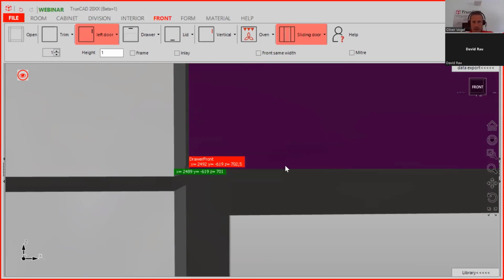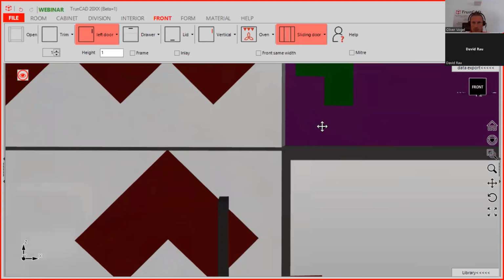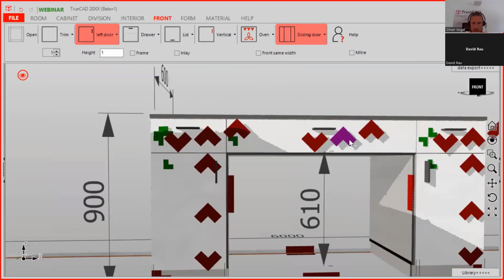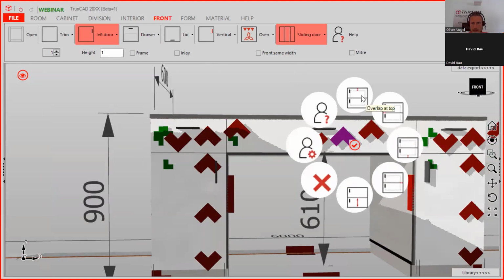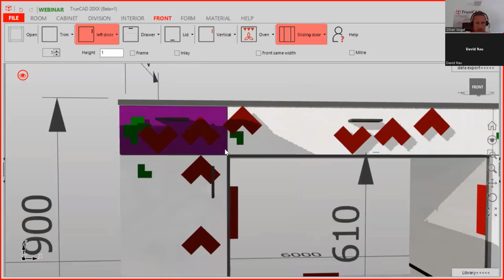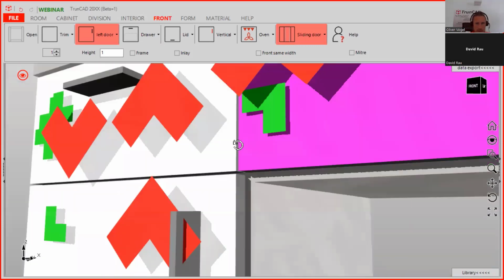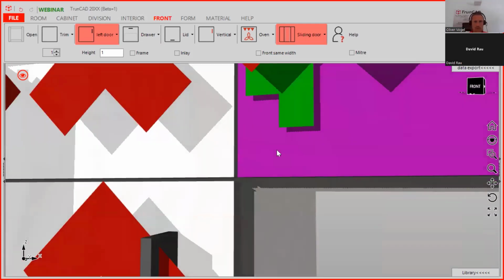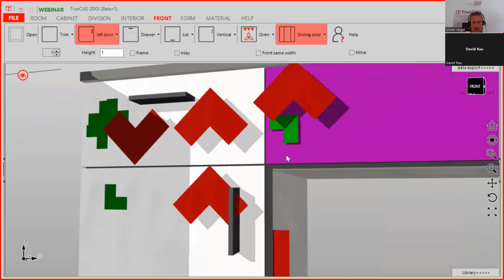Now we just click OK, and we go to a smart click for this. Here you see overlap top, left, and here we want to have it to bottom. And here we can extend it with 1.5 mil. Type it in and confirm it with enter. And then you see it's on the same level. I think we don't need to measure it again.